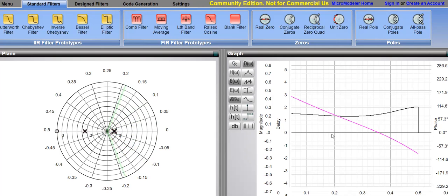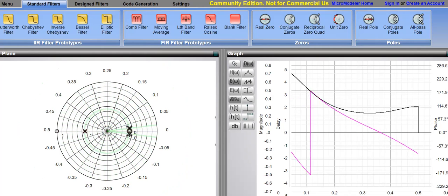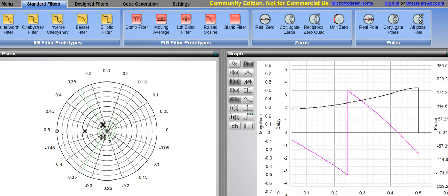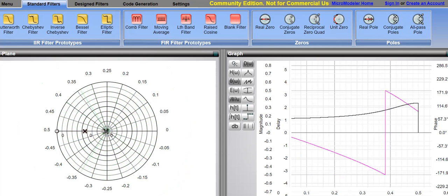You found that almost all the places here, yes, there are some problems. Of course, you need to define the frequencies. Almost from 0 to very high frequency, the group delay remains constant, because you can find that the phase response is almost linear from almost 0 to some other values. You can tune it in a way so that you can find the linearity almost everywhere.